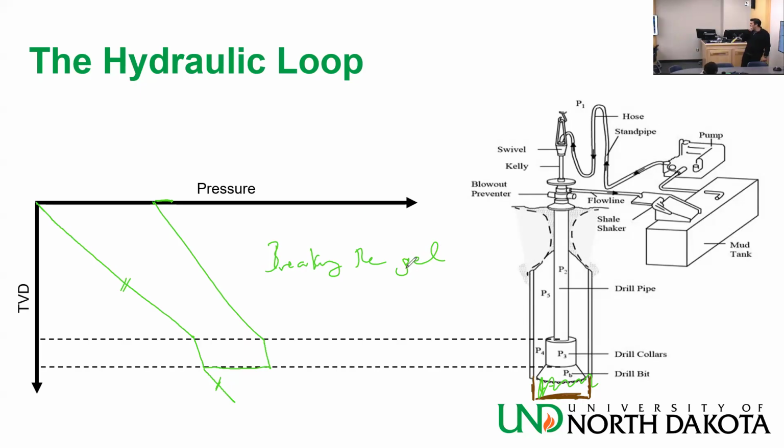And the homework too, the data I gave you to build your hydraulic loop, the model I used to generate that data ignores any turbulence at the bottom of the bit. So in this part here, this little caret at the very end is only hydrostatic losses. So you only gain because of the depth, you gain more depth, and then you lose it by going up. It assumes that there is no turbulence, no frictional losses here. And that's how the model is. It's an old model.